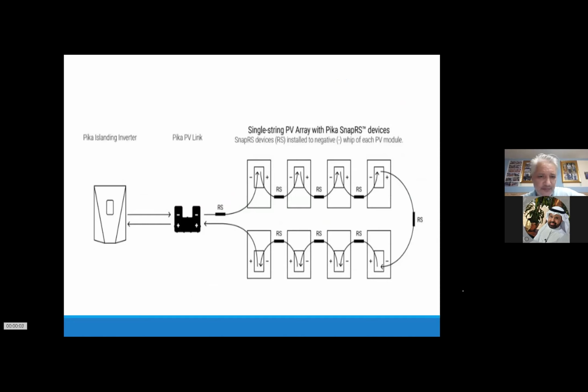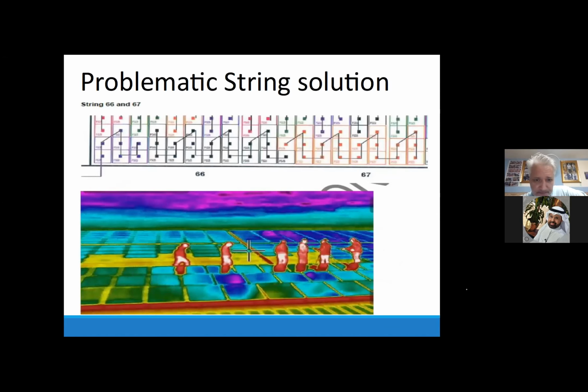These are different devices. So you have inverters. This is again in America, where you have rapid shutdown. Either it's one single unit or each individual module has one of these devices plugged in, like Tigo, I think. There's no other functionality, just that when the inverter or the AC has a blackout, they will shut down either each individual module or the whole string. That's the string solution people used.